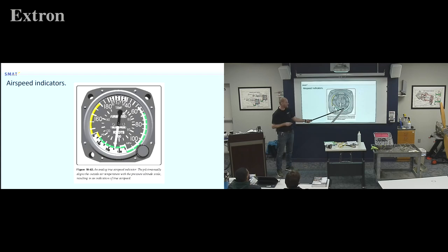You gotta watch these close, because depending on the aircraft you're in, they'll usually give you both. So this one has mile per hour out here. It has knots on the inside. And if you're to look close, 100 is here, 120 knots is here. So on the knots scale, 120 knots is further out. What's this number? 140. 120, look at the inside. Oh, okay, yeah, sorry. You're right, 120's here for knots. So we're only doing 105 knots, is what it's saying.